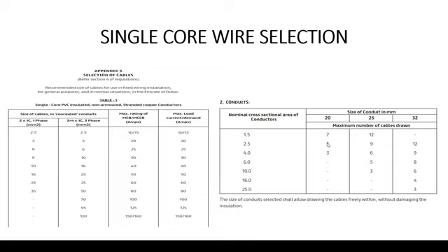If I have to use more wires, for example multiple switches or an extra number of points in this light circuit, I would go for 25 mm, which can take up to 9 number 2.5 mm wires. Again, you can see for the 32 mm. So you need to keep in mind the suitable size of conduit, which can take the number of wires for your circuit.